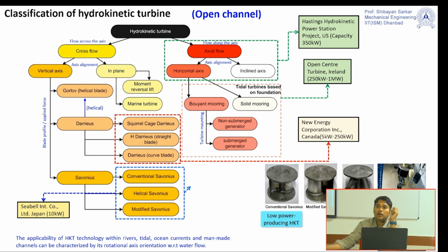If you remember, we have our efficiency curve. On the y-axis there was the coefficient of power or coefficient of torque, and on the x-axis there was TSR, tip speed ratio. That means the ratio of the tip velocity to the fluid flow velocity. The tip velocity is actually the blade velocity. It occurs because of the radius r from this point to this point multiplied by omega. So it is rotating with an omega, and this omega is controlled by the weight imposed by this. You can see this weight here.